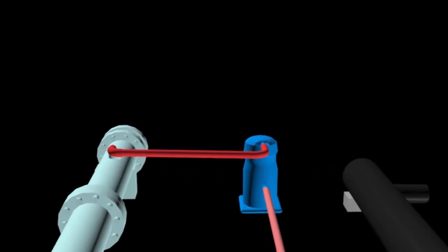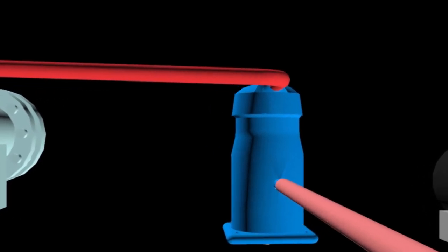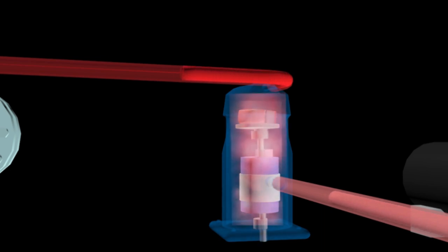In addition, it also serves to increase the temperature of the refrigerant higher than the temperature of the condenser water so that heat transfer can occur in the condenser. The refrigerant enters the compressor as a low pressure gas and comes out as a high pressure gas. The type of compressor used is the scroll hermetic type.